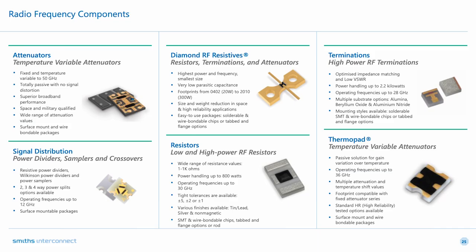The first one here: when considering temperature comp, does it matter if the application is wire bondable or solderable? That's a good question, Katie. Thank you for asking that. No, temp comp is the same for both. It doesn't matter whether it's wire bondable or whether it's solderable, and that's actually why you don't see a selection for that in the ThermoPad tool.